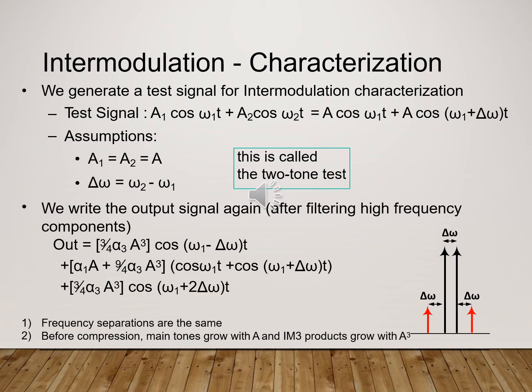Now, intermodulation in general, as we said before, occurs when two or more signals are used in a nonlinear system. So the spectrum at the output of a nonlinear device will not only consist of the original signals, but will also contain the sums and differences of the input signals along with their harmonics. These new components might affect the adjacent channels, and it will be hard to get rid of them.